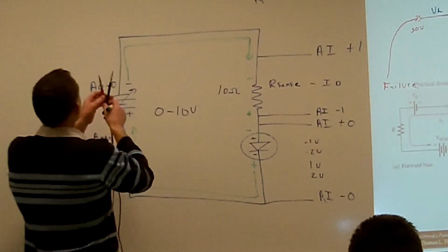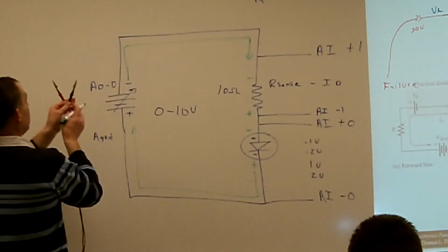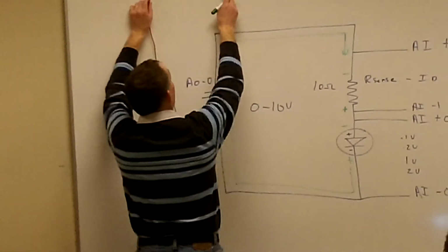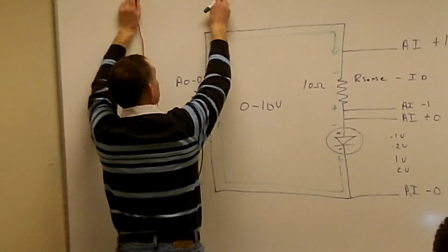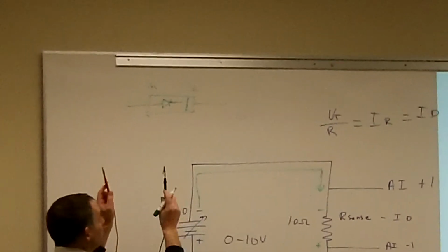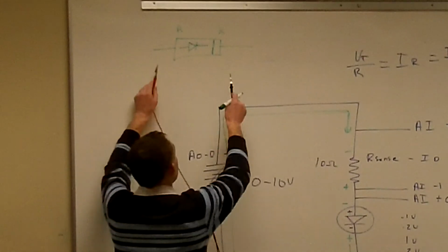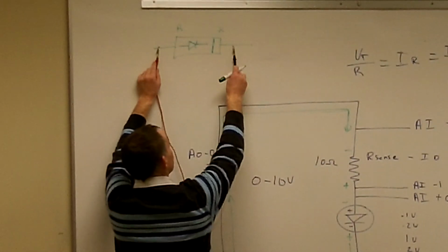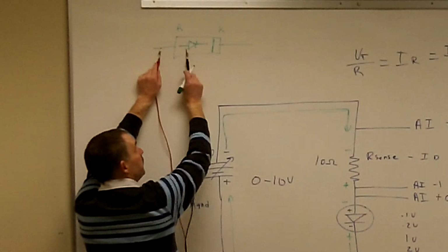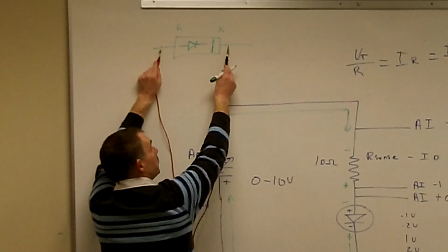So it's kind of the same thing here when I'm doing a diode check. All I'm doing is putting my ohm meter across it. It's going to send a voltage across it, and on most ohm meters there's enough voltage to overcome that 0.7 volt potential barrier. So there's enough voltage to get that diode to start to conduct.